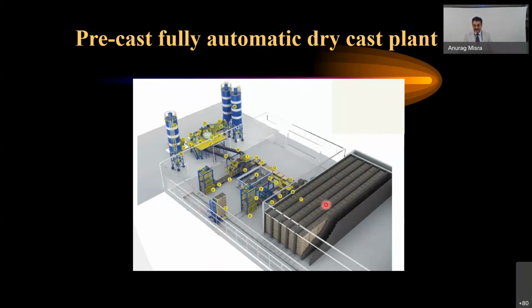It comes here. This curing chamber is not using water. It is using the same water which has been used in the concrete, because this is all a sealed chamber, and within that it creates humidity, and that humidity is maintained here. And once it goes out, and you have to achieve maybe, let's say, M30 grade of concrete, many times we design in a way that this strength is achieved in 24 hours. So the production time is very fast, and you could create for bigger infrastructure.